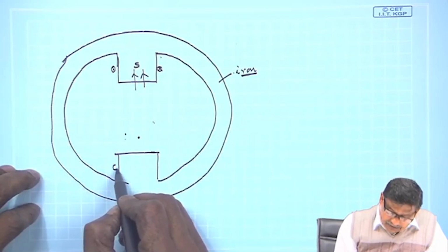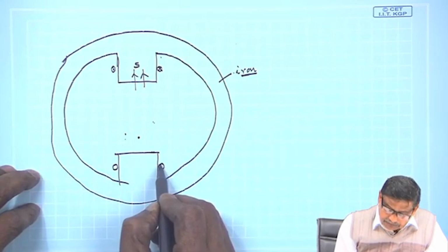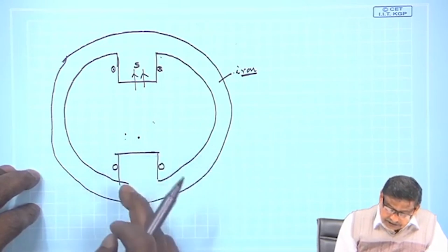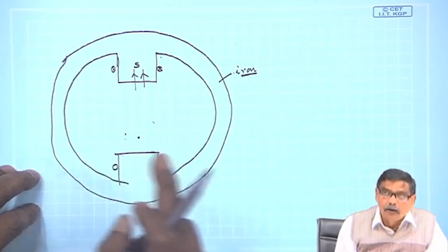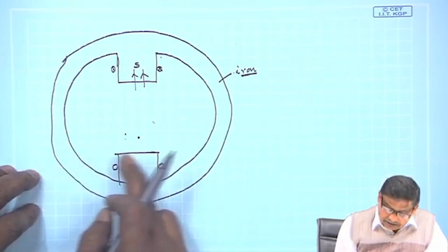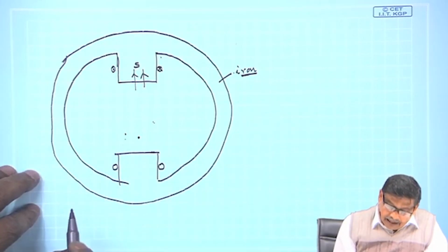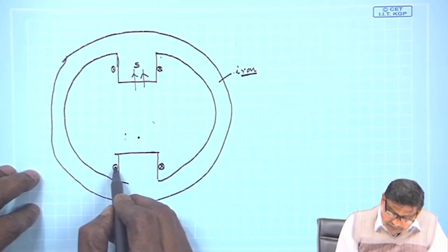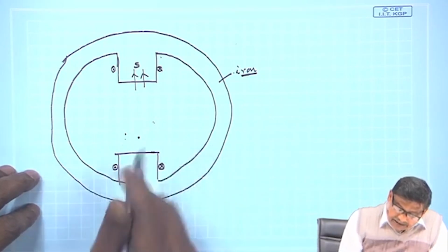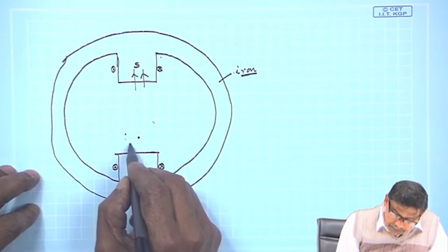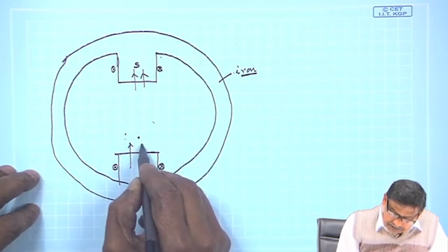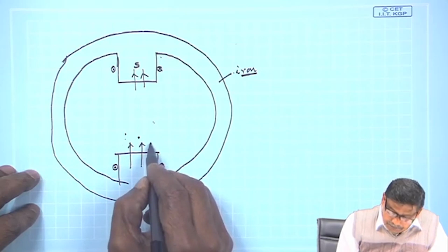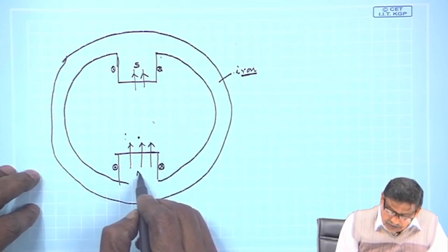Similarly, on the opposite side, in this projected pole, you wrap a coil around it and you pass a current like this, cross and dot. Then the lines of force which will emanate from this will be like this. So, this will behave like a north pole.